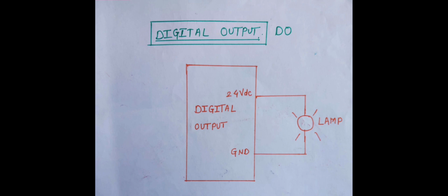Now let's dive into the analog input. The input instrumentation is used in the control system, and in instrumentation as well. Instrumentation devices generally support 4 to 20 milliampere signals. Why is the 4 to 20 milliampere signal used? Because previously 0 to 20 milliampere was used, but the disadvantage of 0 to 20 milliamps is that